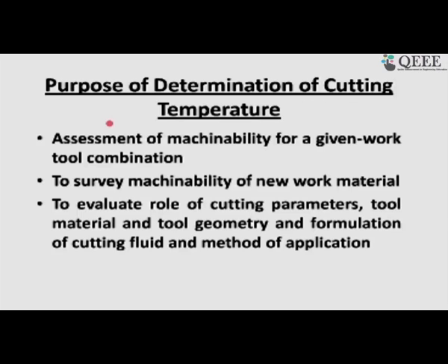So, when it is cutting temperature, it is both the energy because of the deformation in the primary shear zone, and also the energy spent in the chip tool interface, which is called a secondary shear zone because of the stagnant friction at the chip tool interface, that becomes almost another source of heat. So, how this fluid can at least bring down the temperature considering the friction aspect at the chip tool interface, or overall temperature can be brought down by its cooling effect.